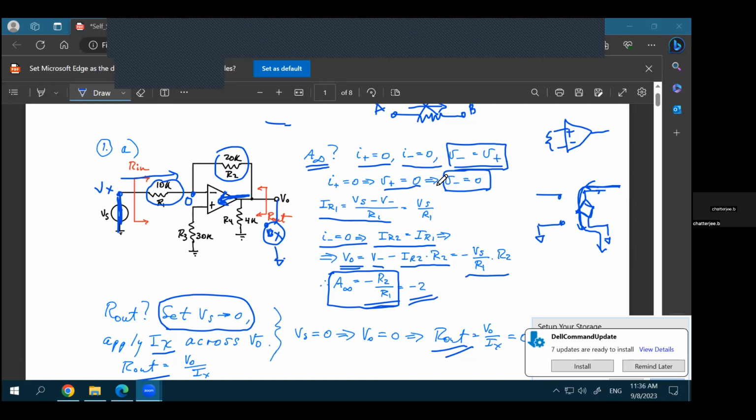Now you divide your numerator and denominator both by A beta. So what do you have in the numerator? You have 1 upon beta. What do you have in the denominator? You have 1 upon A beta plus 1. And that's what we are writing here. It's the same equation. It's just that because there are so many different terms involved, it may look a little confusing in the beginning. But if you work out a few problems, it will be very clear that your 1 upon beta is exactly equal to A infinity. Your A times beta is equal to this. So these two are the same equation. All of them are the same equation.